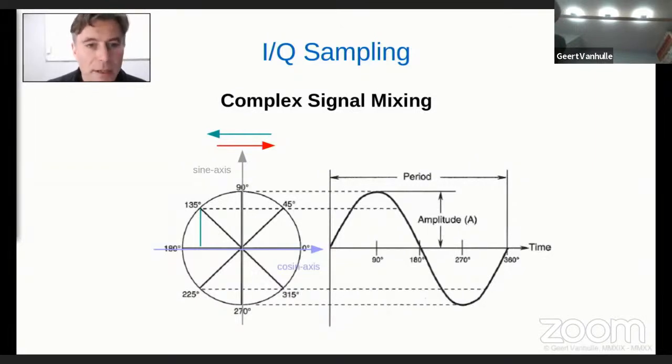But what is actually happening is that 90 megahertz minus 100 results in minus 10 megahertz. Of course, minus 10 megahertz doesn't really make sense in the time domain. It's just the same thing: a single sinusoidal wave that is progressing in time and changing in amplitude. However, in the vector field, we can see that if we had 110 minus 100 megahertz, we would have a vector rotating in a counterclockwise direction.